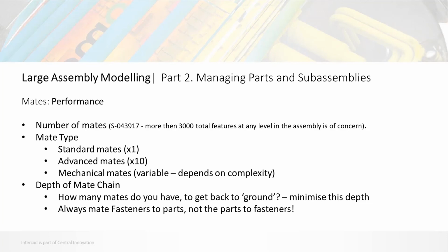because they do solve in a specific order, and if there's a long length of them, then it's going to take longer to process. And one other key thing to remember here is to always mate fasteners to parts, not the parts to fasteners, simply because of that depth of the mate chain issue. Fasteners should be things that can be removed without impacting the assembly. They shouldn't actually be holding it together.